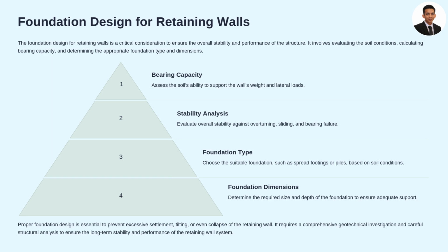Number 3. Depth of foundation. The foundation must be deep enough to prevent issues like frost heave or scour. In coastal areas, this often requires additional protection against erosion.